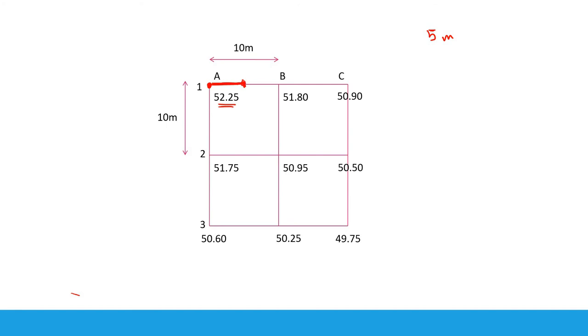And then we will locate a point. And then we will move to the next, between these two nodes. For example, if I aim now to draw the contour line of 52 between A1 and A2, this is A1 and this is A2. Do I have 52 contour lines? I have 51.75 moving to 52.25. Okay, I will pass through 52 somewhere, so I need to calculate 52 location. It would be somewhere here, for example, and then we are going to draw the contour line.